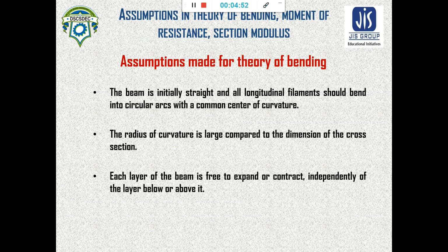That means each and every fiber of the beam, each and every longitudinal filament, should bend into a circular arc with a common center of curvature. So the center of curvature should be common.